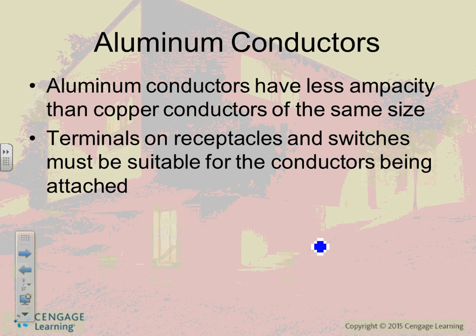Okay, aluminum. Like I said, with aluminum conductors, the utilities use aluminum all the time, guys. They have the crimp connectors, they use them and they're used successfully. Aluminum conductors have shown in the industry that they contract and expand at a higher rate. If you have a lug that expands and contracts at a higher rate, over time, what's going to happen to the wire? It gets loose. Loose wires arc and spark. If you're lucky, your short circuit breaker will take care of it. If you're not lucky, you start a fire. And it's highly unlikely, guys, to start a fire when you're arcing and sparking in a box like this. I mean, it will take a long time to burn this. It's made to handle good heat. That's why they want you to put them in a box.